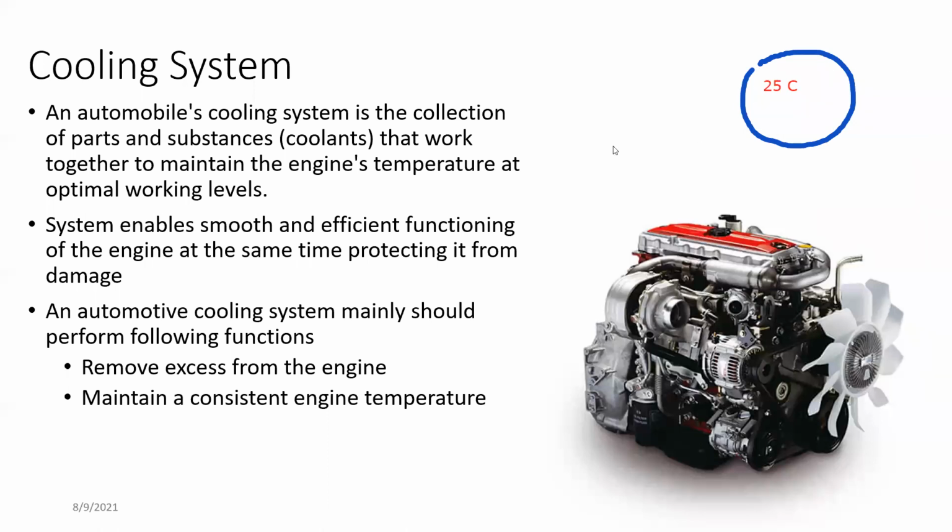But once the engine is started, the temperature increases. There's a particular temperature that the engine needs to run properly. So at that particular temperature, this gap will be fully closed, right? Fully closed. So now there is no leak, or no contact, between the combustion chamber and the crankcase. So it's fully closed.